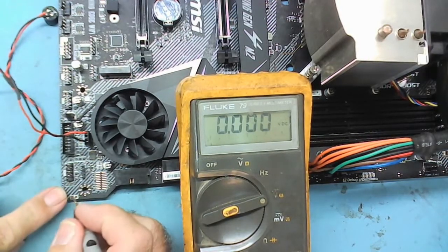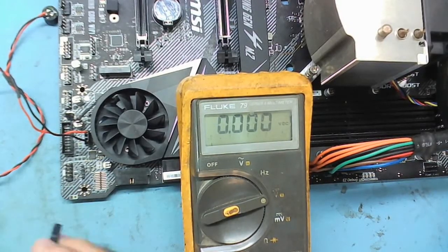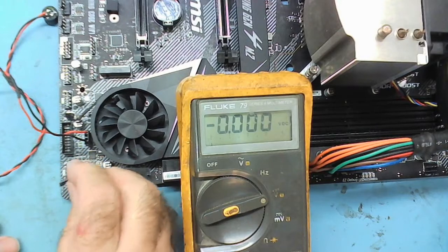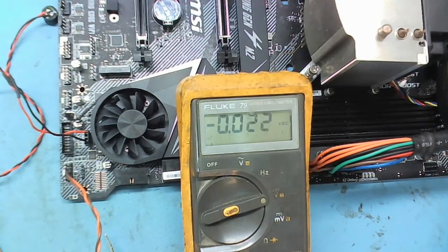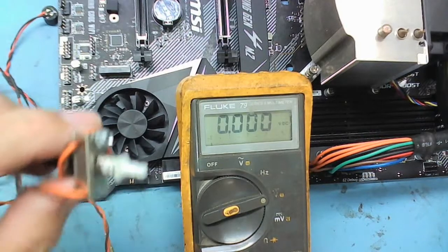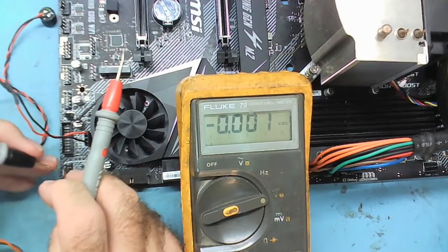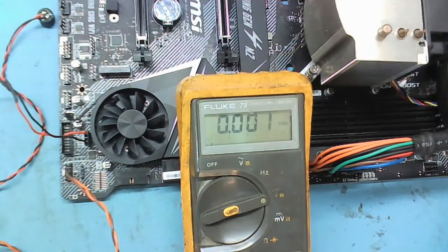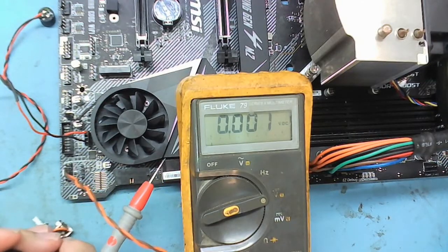I mentioned before that I'd show you how to figure out where the start button goes if you haven't got a manual and you can't find out. The answer is the pin that's got 3.3 when it's not switched on to ground. That's where the start button goes. So we've got 3.3 here, and I'm sure we can see quite clearly if I can get a connection onto the switch. Easiest place. Told you a good reason for having a switch, didn't I? On the switch.